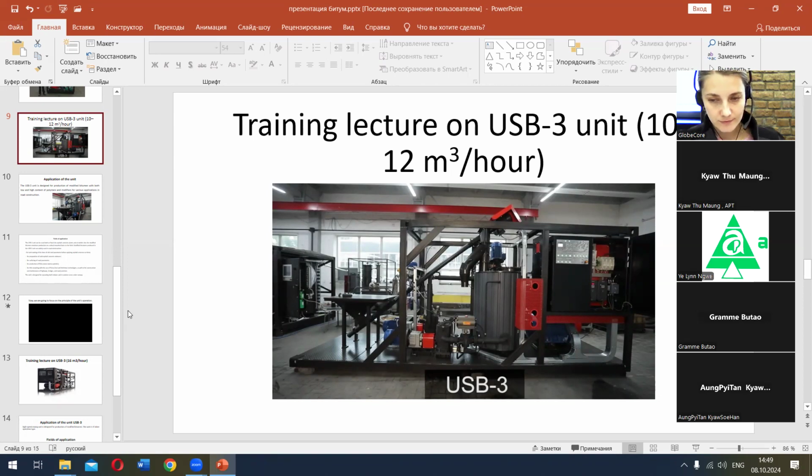Okay, great. That is quite clear, which means if I've understood it clearly, after the processing from the agitators within the processing unit, we need to wait about 40 minutes till we dispatch the product either to the storage tank or to the road tanker for deliveries, right? No, but you can fill it to the storage tank right away. But before using that product, you have to wait at least 40 minutes. So it's when it will achieve the required condition to be used.